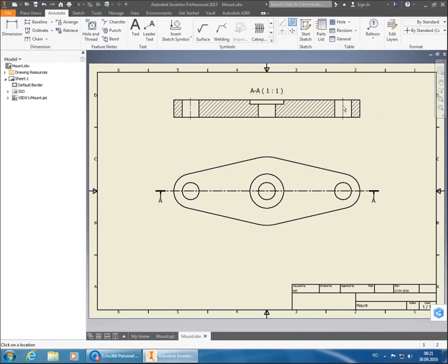The problem now is if I do the same in the middle one here, I'm not going to get a center line all the way through because I don't have lines going all the way through. So there I'll use the irregular centerline function instead, the one up here. And I'll click on the top and then click on the bottom and then right click and create, because then I get a proper centerline through that one also.